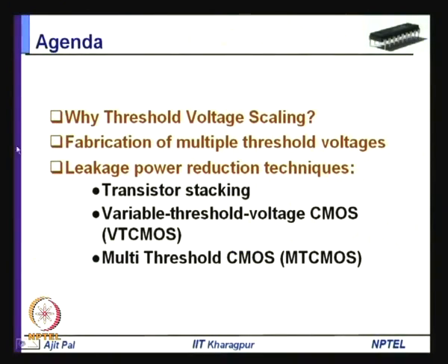So, here is the agenda of today's lecture. First I shall discuss why threshold voltage scaling. As we shall see, threshold voltage plays a very important role in minimizing leakage power. So, we shall discuss the role of threshold voltage and how threshold voltage scaling can be done to reduce leakage power. Then we shall discuss various techniques for fabrication of multiple threshold voltages on a single chip, and that is necessary for realizing low power circuits, particularly for minimizing leakage power.